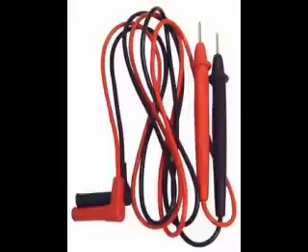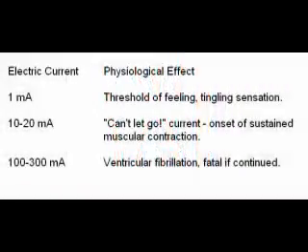Resistance is the measure of friction to electron flow through an object. The less resistance there is between 2 points, the easier it is for the electrons to flow between those 2 points. Given that electric shock is caused by the large flow of electrons through a person's body, increased body resistance acts as a safeguard, making it more difficult for electrons to flow through us. What can we ascertain about electrical safety from resistance readings obtained with wet fingers? Does water increase or decrease shock hazard to people?